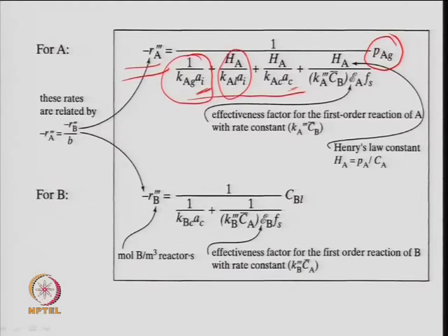So, one can do the hydrodynamic study and one can find out the mass transfer coefficient, and accordingly again the interfacial film thickness, which is, as I said, just a simple example, smaller the bubble. So, if you have a bubble column reactor, you design a good kind of sparger. Same thing for the trickle bed reactor, you need to design a good kind of distributor, right. So, that is KAG, KAL, which are related to the empirical formulas, or can be calculated depending upon the hydrodynamics, and one can control these, or one can maximize the coefficient or minimize the resistance, because these are nothing but the resistances offered by each step, and this step is your overall resistance.